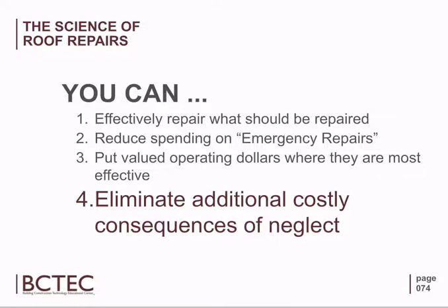So, Craig, we saw that hotel that Fortune 500 was running. Do you think that was a cheap fix to get all that mold remediated? No, that's neglect on your roof. I couldn't imagine what the cost would be there. Again, if you had that preventative maintenance program, you can capture those little pinhole leaks in the beginning. The wall looked like that. Imagine what their roof and their roof deck looks like. Yeah, we could have major structural deterioration on the roof. We've got a metal deck, severely corroded. Could be looking at deck replacement.